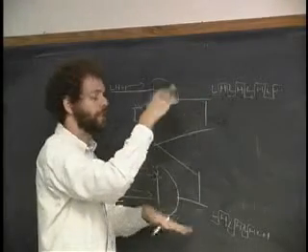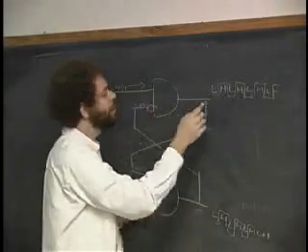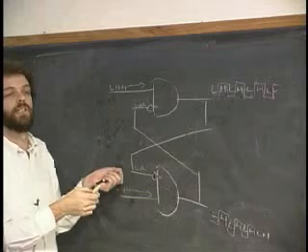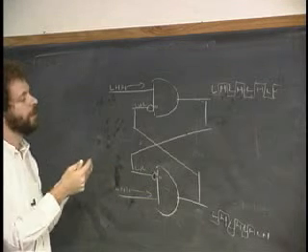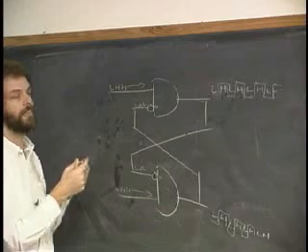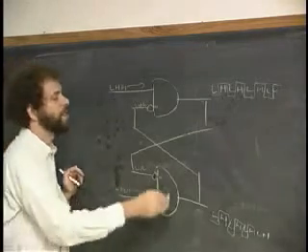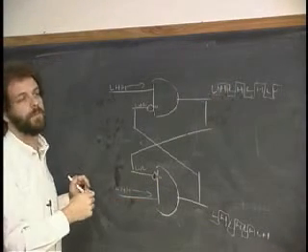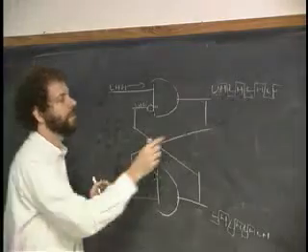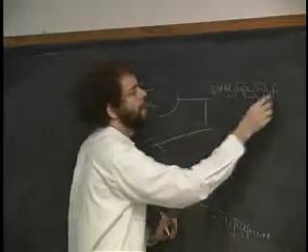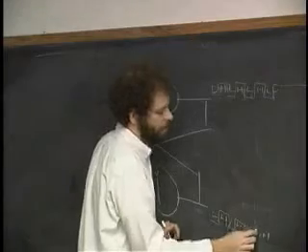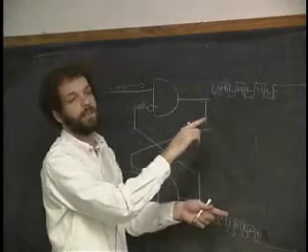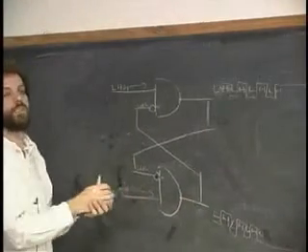It'll ring and ring and ring, flip-flopping back and forth. But eventually, either the highs will grow or the lows will grow. You may think it's impossible, since it's always impossible for two real values in the real world to have exactly the same value. The propagation times of the rising edge and the falling edge cannot always be exactly the same. So it will always tend to extinguish the oscillation, and it'll end up being a value that's high or a value that's low, like that. Or maybe the other way. So even in the dynamic case, the oscillation will die down.